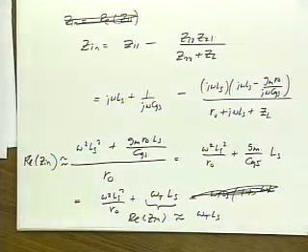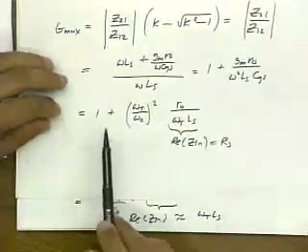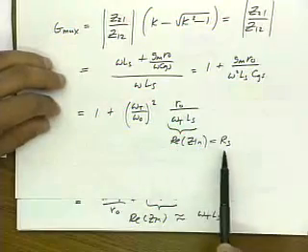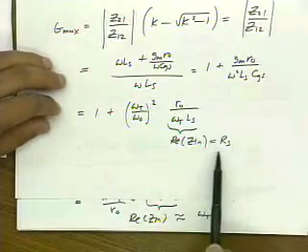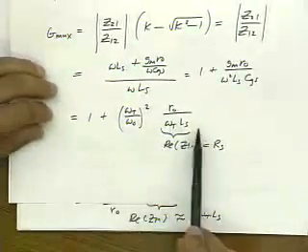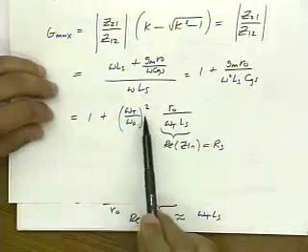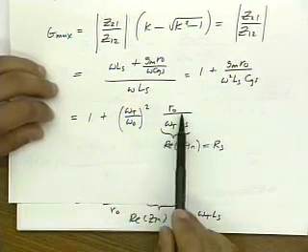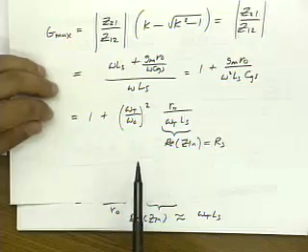Now, we'll look back to the equation we derived here. Here, I said that this is approximately the real part of Z in, which for an impedance match condition is just Rs. And so now you see that the power gain is proportional to omega T over omega naught squared times the ratio of the output resistance to Rs. Okay?